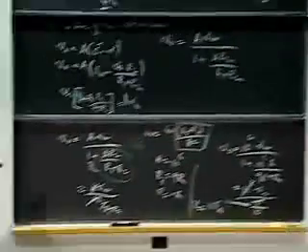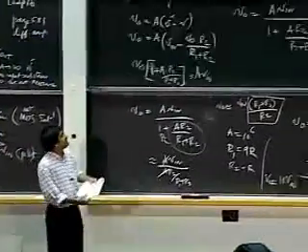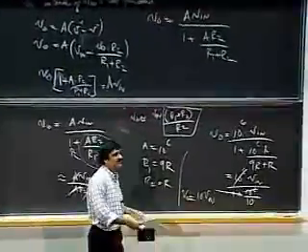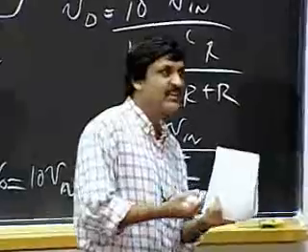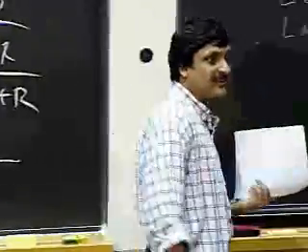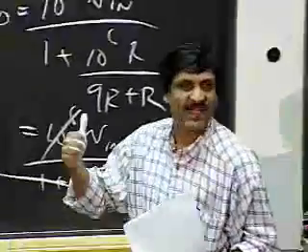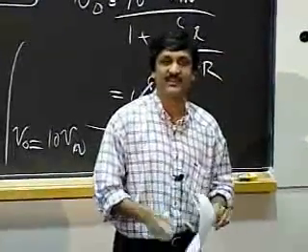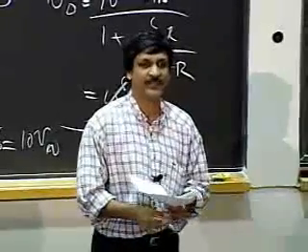So what I've done now is by connecting these resistors in this way, I have a nice amplifier with a gain of 10. Now the question you may ask yourselves is, why? There's a little sucker in there that wants to shoot things up by 10 to the 6th, wants to knock things off to one rail or the negative rail. So why is it behaving like a docile lamb here and giving us a nice little factor of 10 gain no matter what I do to it? Why is it doing that? What's the intuition behind it?